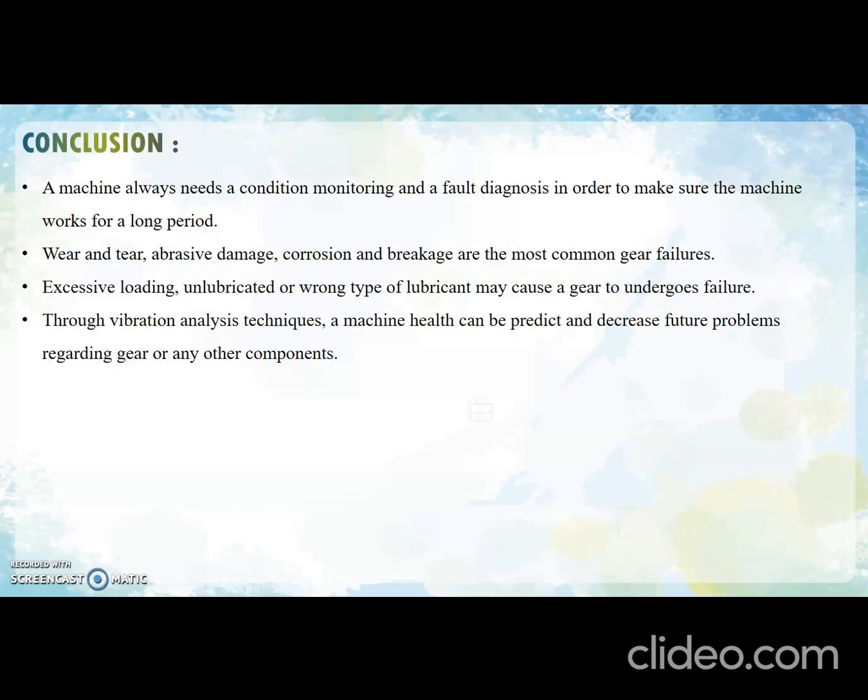Excessive loading, unlubricated or wrong type of lubricant may cause a gear to undergo failure. Through vibration analysis techniques, a machine's health can be predicted and future problems regarding gears or any other component can be decreased.